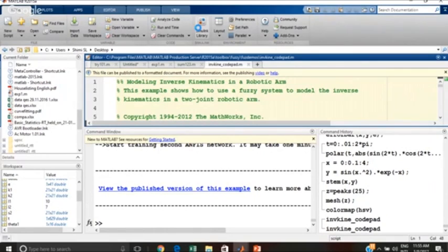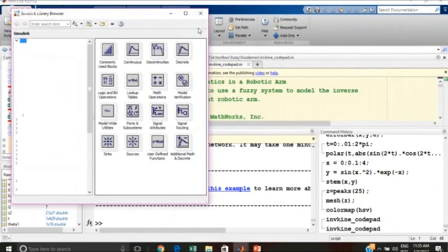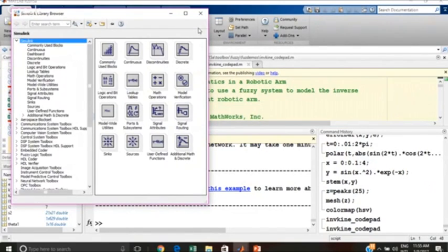Then the controller may be any type of controller, inside it a PID controller, or a microcontroller based controller. All those embedded programs take the voltage and current, compare them and do a lot of things. Once you put all these things in a single sheet, you yourself will become confused about what is what. So what we do is make subsystems. We make a motor, select all those things and put them inside a block, and we say that is a motor. Then the power supply and all the accessories we put inside another block and say that is the power circuit. Then we put all the control circuit inside one.